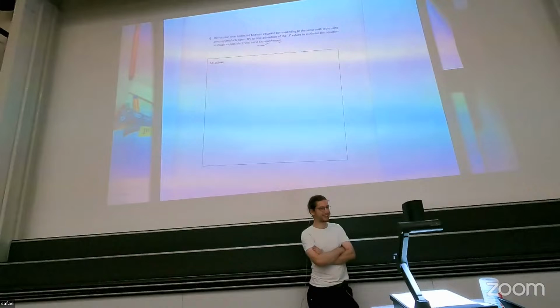In real life, when we make test benches, the whole time is usually tiny, so people say, why don't I just put it as close as I can before? But in a real circuit, where circuits have delays, signals inside the chip can get delayed a little more than you expect.